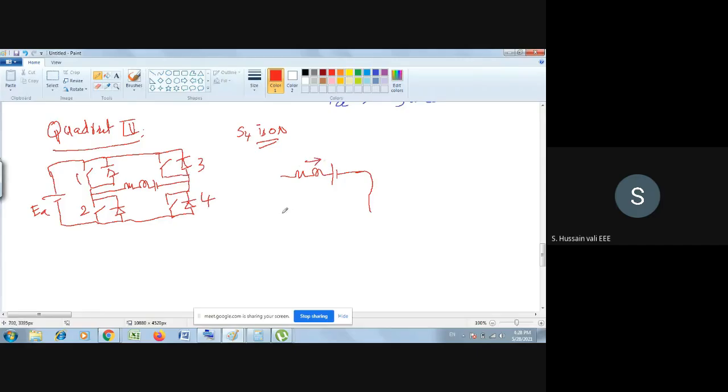The direction of the line, plus minus. So it will conduct through D2. So this is E naught. E naught is equal to 0 this time, because S4 and D2 are conducting. No other switch is there. So S4, D2. There is no other option left, because no other switches or diodes will conduct. So the only option left is that it will force D2 to conduct. Then this is the direction of the current.